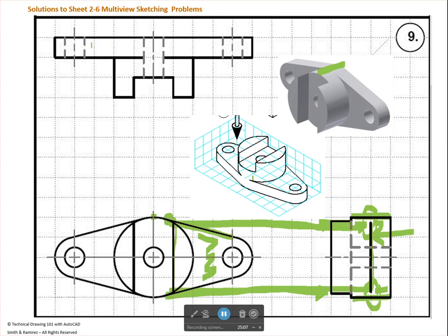So here's what's happening in the top view. You have this edge here and this edge here, that plane. It's running uphill, and it's running uphill on this side. And it doesn't make it all the way to the top. You can see it comes up and then it hits the tangency. So we look and we find that tangency point and we project up. And that's how far we know this line comes up, and then it becomes a run out in there, so there's no hard edge. And same way here, we find this tangency and we project up. Now, those might line up with the edges of this hole, but they're separate features.